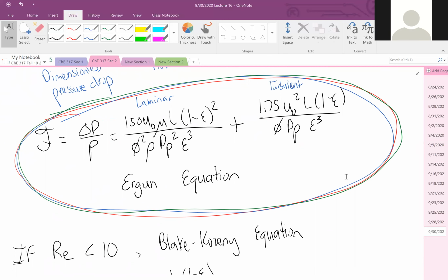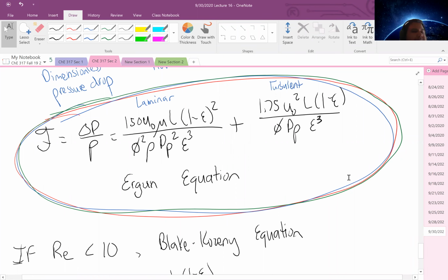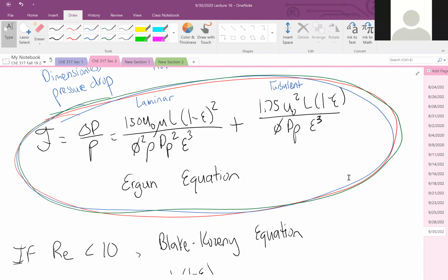Dr. Lopez, I have a question. Go ahead. So normally, if we were applying this equation in reactors, we would do it in increments, and then our density would be the density corresponding to that increment. But if you were going to do it all in one shot like this, what density would you use, the inlet or the outlet? You would typically want to use an arithmetic average. Okay.